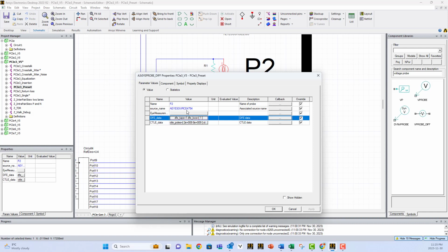So that's why you need to connect it to one source so they communicate with each other until this value is optimized. DFE stands for Decision Feedback Equalizer. The FFE and the DFE are mainly used to compensate for the memory of the channel. The memory is there because of the intersymbol interference and the poor transitions in the PCB.